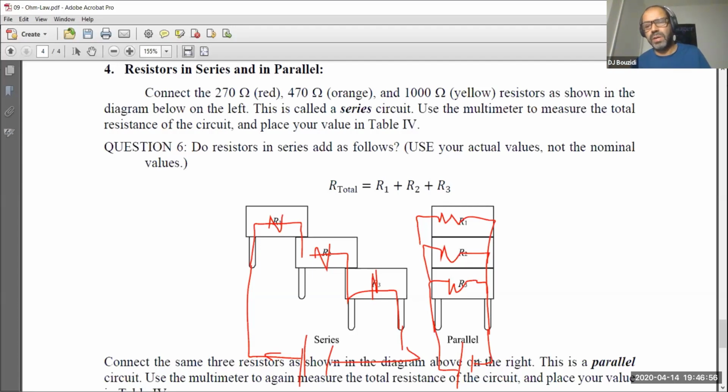This is the conservation of charge, which is one of the fundamental laws in nature. Versus this case, where the current comes in, say 10 coulombs, 10 charges come in here, and they all merge through this resistor together. They come in and they all move through this resistor together. So the charges or the current are the same in the series. I is the same. Whereas in the parallel case, I is not the same, but the voltage drop is different.